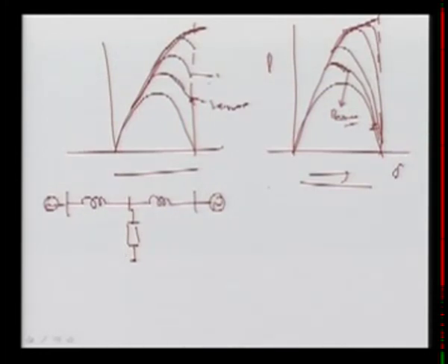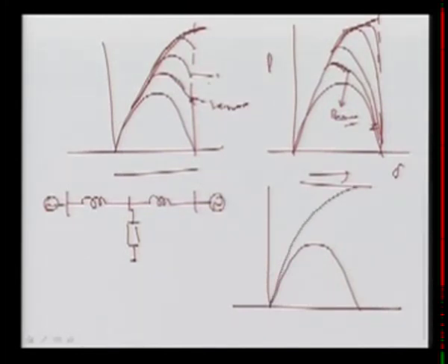If you remember, now again I can draw this P-angle here. This is without compensator. If we are using a compensator, what is happening? Now we can go for this much. Our system was operating with the mechanical power here, and now this value is 0. After a certain time the fault which occurs at this bus is cleared, and your system will be coming here, and then this area must be equal to this area, which is your A2.